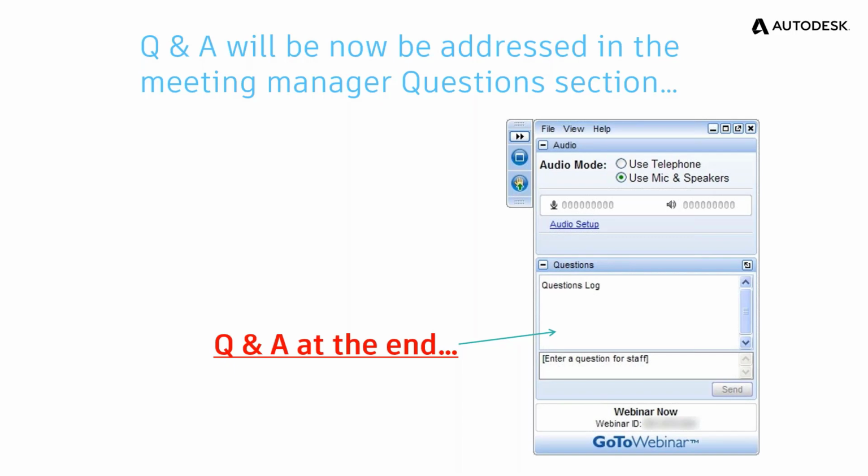I'm going to go back to the question: if you insert a dynamic block into an existing drawing with a block of the same name, will the existing blocks move? One catch, if you have a drawing that has a standard block named door, and then you try to drag and drop a dynamic block from another drawing also named door into the first one, it's going to want to overwrite the door that's in there.